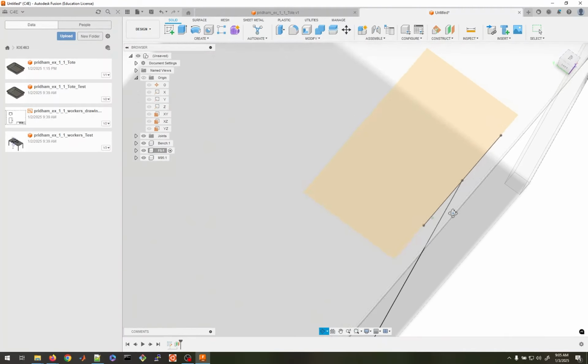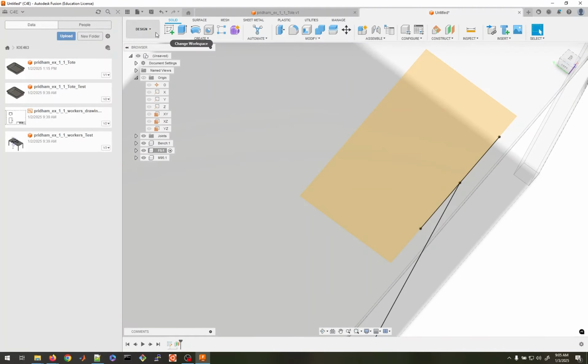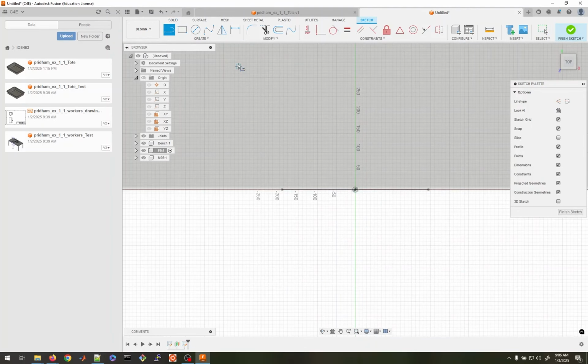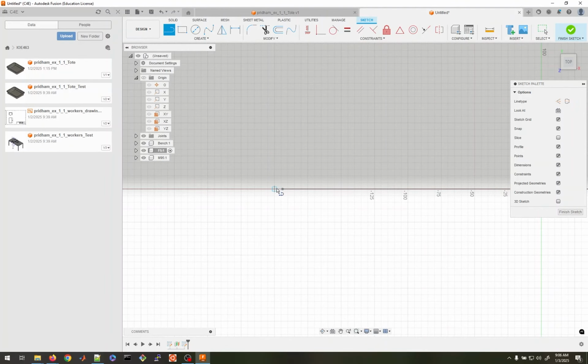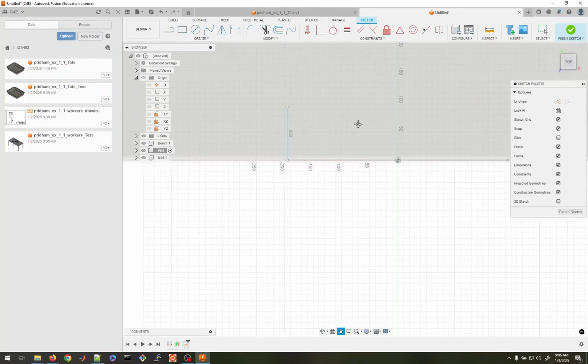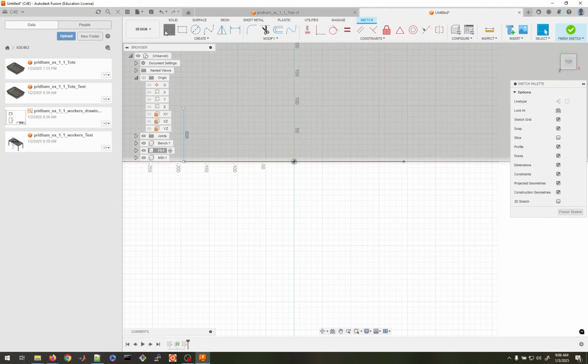And now I'm going to draw arms on that plane. So come up here to create sketch, select it, select the line, and draw a line there, hit escape, come over here, draw another line.